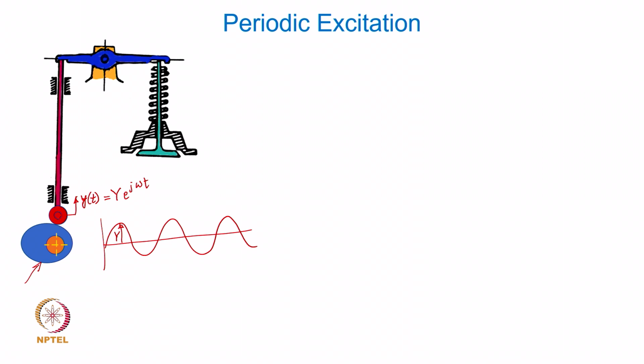It should not have a heavy jerk and so on so forth. So, the profile of the cam would not really generate a base motion of the follower which is harmonic, right. So, this particular assumption of ours that the base is going to move with a harmonic pattern or motion is really not strictly valid in all cases, of course.